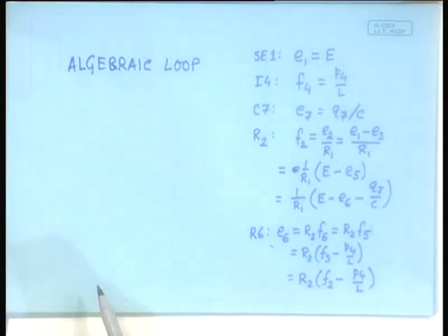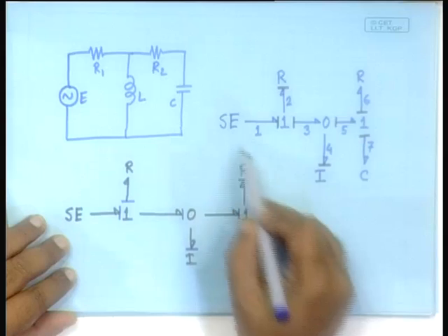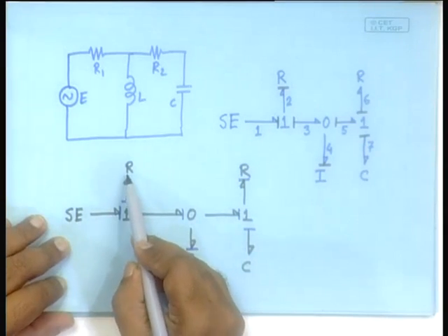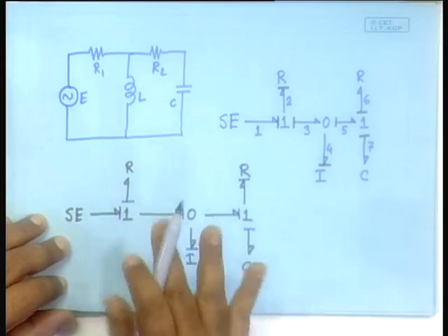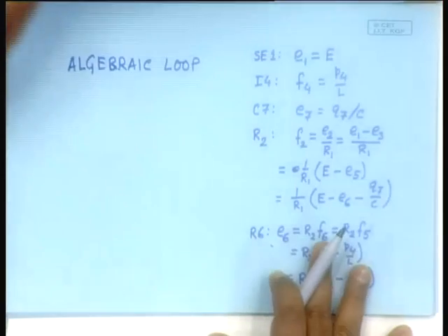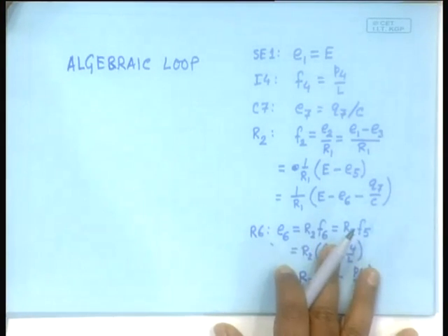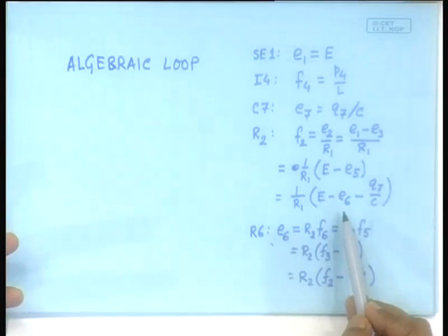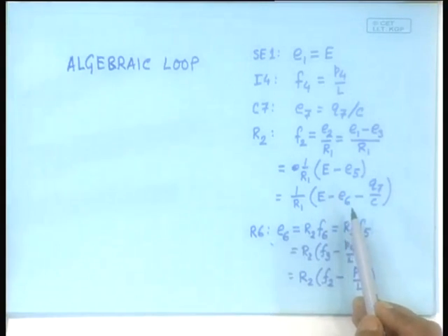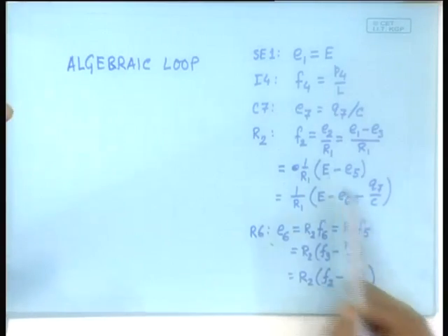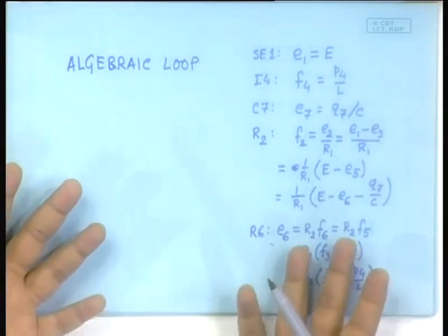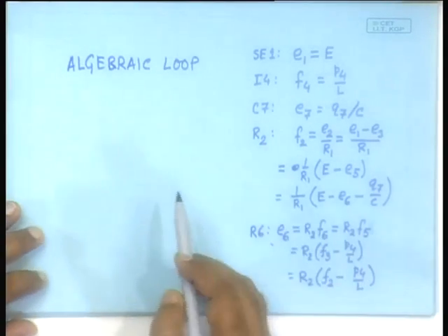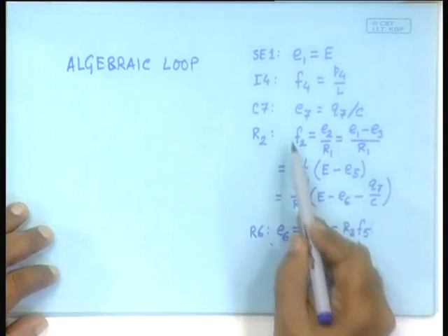And whenever there is an indeterminacy of the causal structure, so that you are having to, out of your hat, put a causality in one of the R elements, it immediately indicates that you will have this kind of problem while obtaining the differential equation. But you would notice that that is not a big deal. Why? Because you have two equations and two unknowns. The moment you have two equations, two unknowns, you can always solve it and obtain these two individually. So, they are actually determinable, no problem, but you have this causal loop. So, how do you obtain this? Can you just do this bit of algebra to obtain this individually?